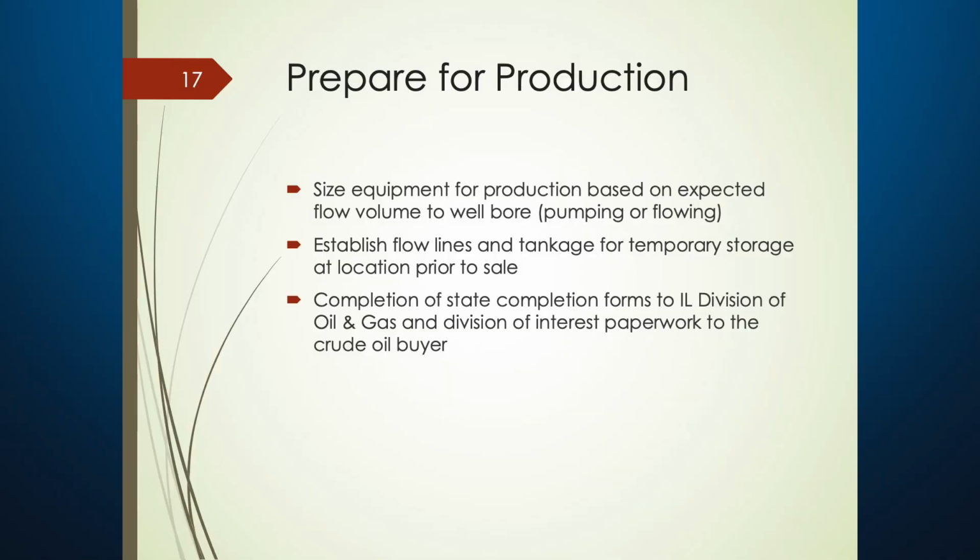Okay, how much oil is it going to produce? We test the well by swabbing. It's actually just kind of a temporary pump. It goes in, it's got cups on the bottom, and it pulls up through the casing, and you actually recover the fluid that comes through the perforations. So that fluid comes into the wellbore, we pull it out, we get a test, calculate our percentage of oil, percentage of water, get a show of gas. Do we have gas to surface? Do we have 1,200 foot of gas in the hole? All of these things are recorded.